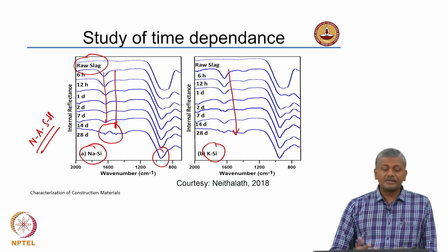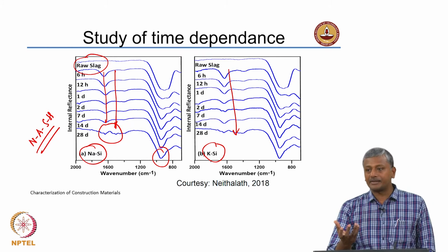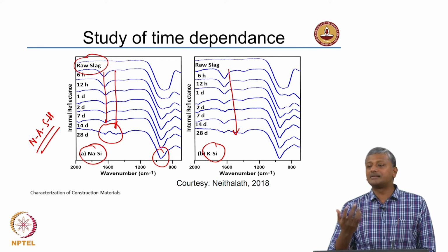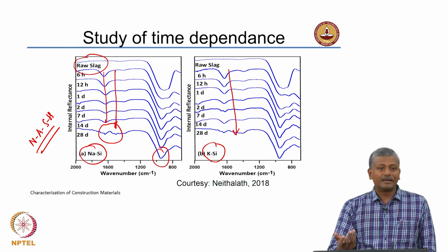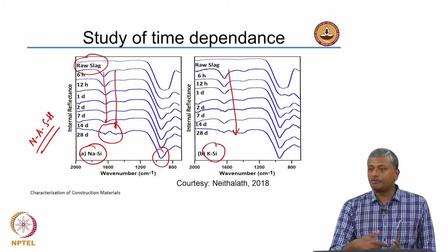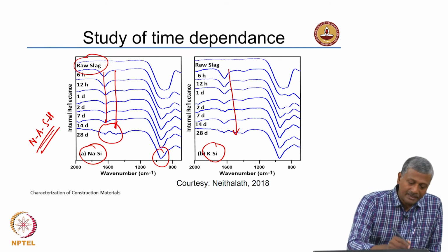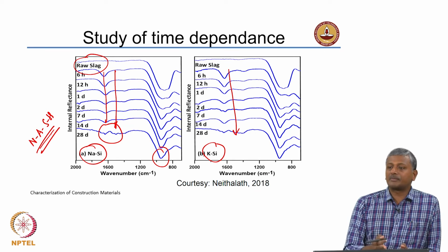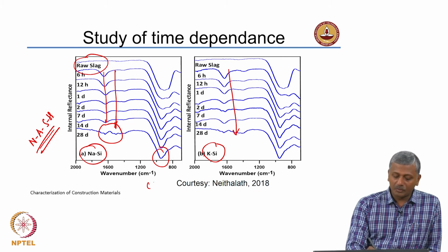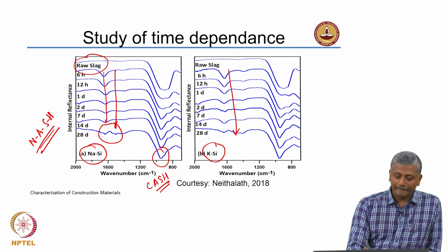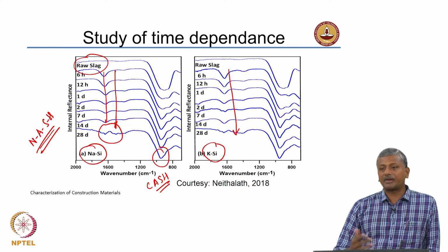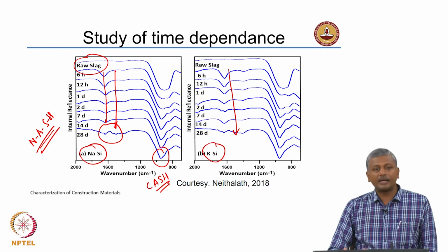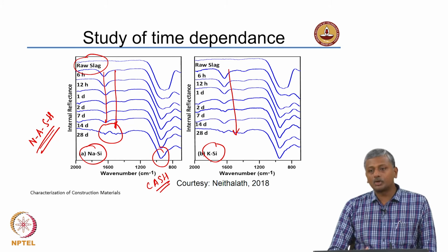So, what this goes to show is when you have these alkalis, sodium or potassium, they are trying to increase the rates of dissolution of the slag, right, but they do not really form major complexes such as NASH in the species, because what happens overall is that your system ends up forming calcium aluminosilicate hydrate. Unlike in the case of fly ash or calcined clay, where your alkalis geopolymerize the system and produce compounds such as sodium aluminosilicate hydrate.